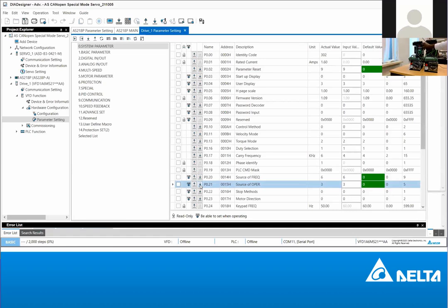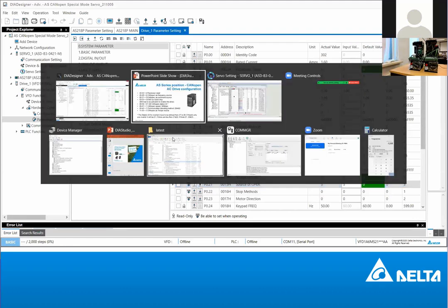I don't know if you can see the display. Let me check those parameters on the display. Parameter 0020. Parameter 00 is 0. Let's go to 00. Let's go to 20. So I should have 6 here. Perfect, 6. If I go to 21, I should have 3. Perfect. So that's okay. So what's the next step?